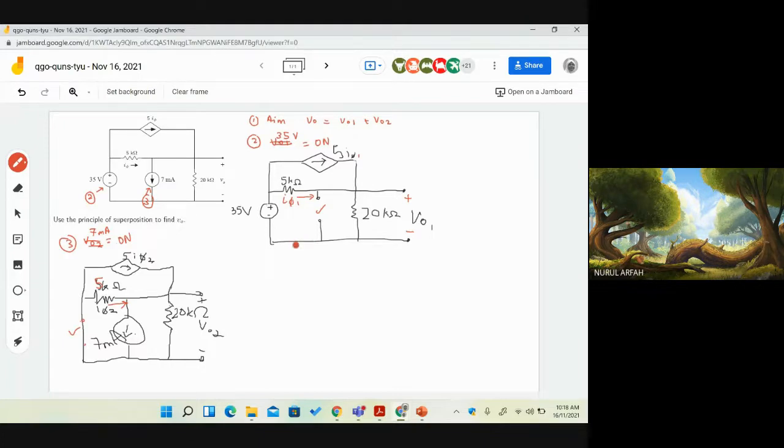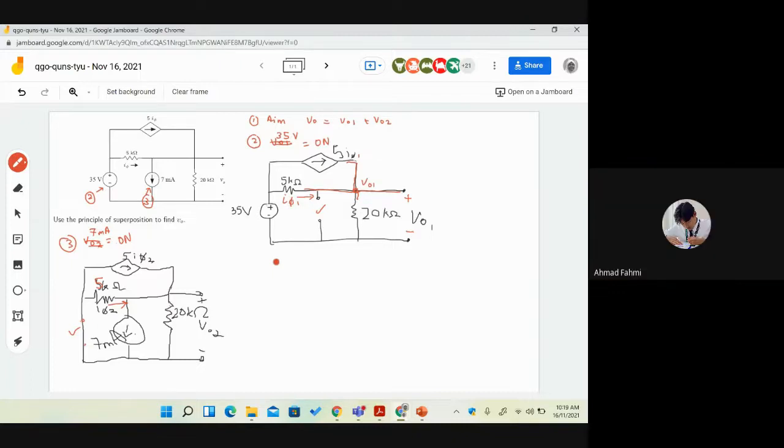I think nodal, right? Because if you use nodal, then this one becomes V01 here. All this node here is V01. How do I know it is V01 here? Because of the reference, the bottom is 0, ground.